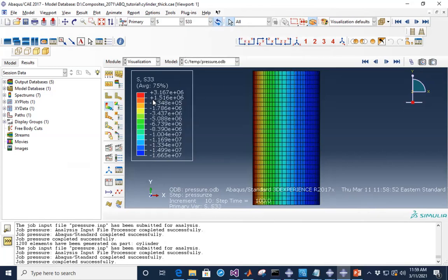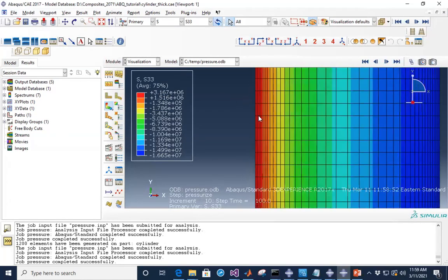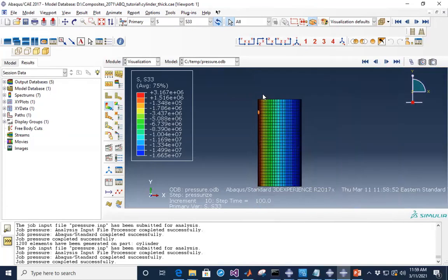You see now it's gone back to pretty close to what the analytical solution is. So the analytical solution, remember, is 3.33 megapascal. Now it's gone from earlier we had 2.7 megapascal with the linear mesh. Now because we've resolved it well enough at the boundaries, it's gone back to about 3.17. So that's a much smaller error than what we had earlier.